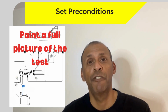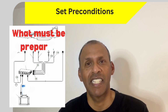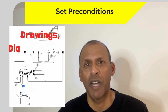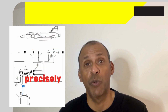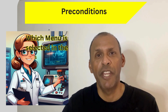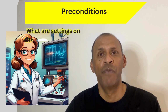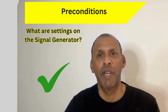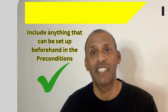The preconditions and setup are where you paint the full picture of what the test environment should look like. What needs to be ready, what's in the setup. Include drawings, diagrams, part numbers, parts lists, software configurations, the whole lot. The goal is that anyone can pick up the spec and recreate the setup without guesswork. Don't forget to include in the preconditions details like which menu must be selected in the software being used, or what setting must be selected on the signal generator. These can be included in the test procedure, but it's usually better practice to include anything that can be set up beforehand in the preconditions.